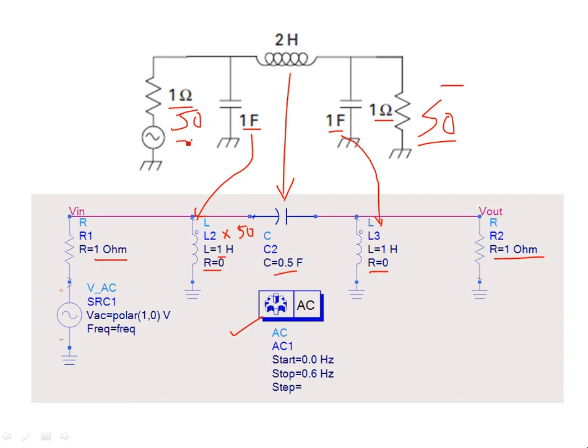So to keep the thing simple, I mean, to keep the power matched at the center passband or from the passband edge, we are keeping the load and the source resistance equal. Okay. All right. So if it's 50 ohm operation, then the inductances are going to multiply by 50, and the capacitance is going to be divided by 50. And then it's not only that, you have to divide this by 2 pi into 5000. Why? You have to denormalize the scale, right? You have to denormalize the frequency scale. So if you do that, and then you have to do this for all the lumped components.